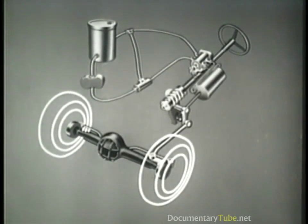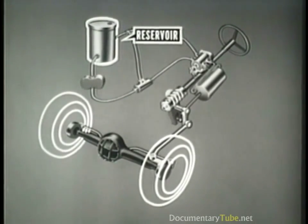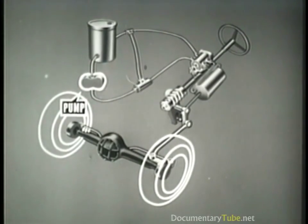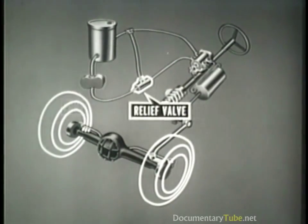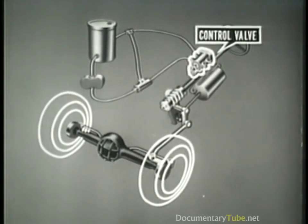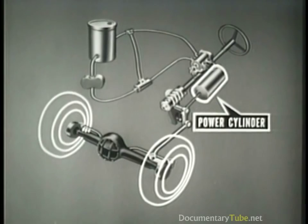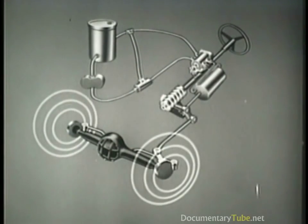Now let us review the operation of the hydraulic steering system. The reservoir supplies fluid. The pump, driven by the engine, delivers the fluid under pressure through the relief valve to the control valve. The relief valve provides an escape for excess pressure back to the reservoir. The control valve directs fluid to the power cylinder. The power cylinder converts hydraulic pressure into mechanical force, which in turn actuates the pitman arm shaft and lever and the pitman arm, turning the front wheels of the vehicle through the steering linkage.